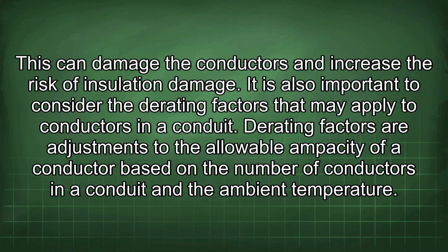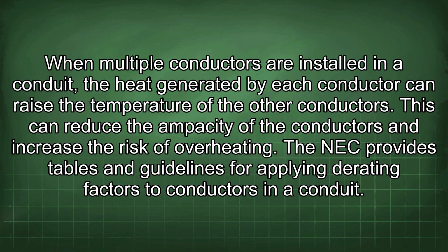It is also important to consider the derating factors that may apply to conductors in a conduit. Derating factors are adjustments to the allowable ampacity of a conductor based on the number of conductors in a conduit and the ambient temperature. When multiple conductors are installed in a conduit, the heat generated by each conductor can raise the temperature of the other conductors. This can reduce the ampacity of the conductors and increase the risk of overheating.